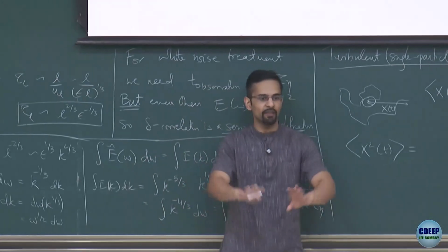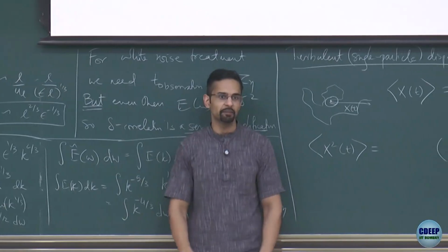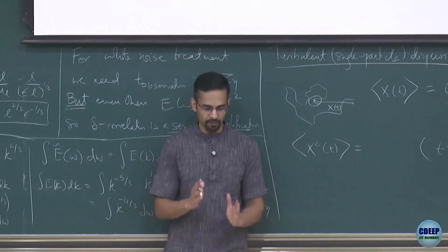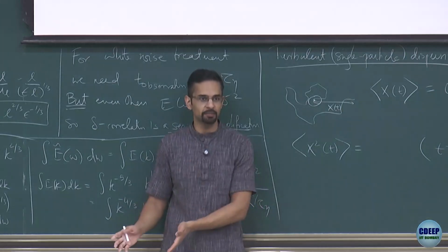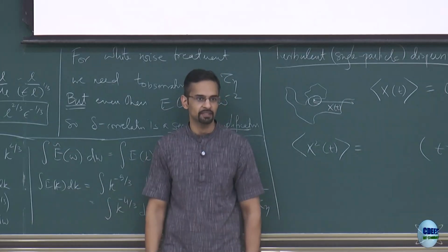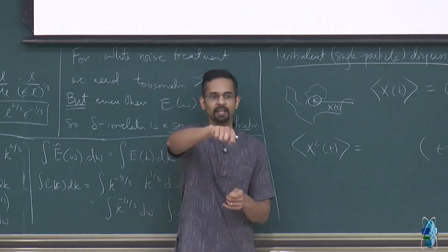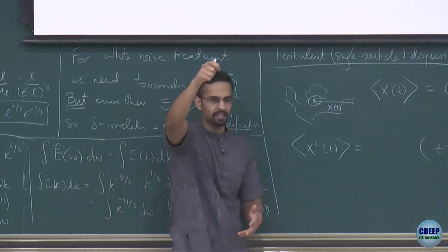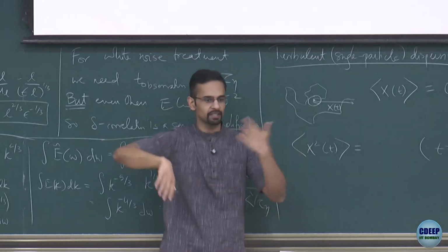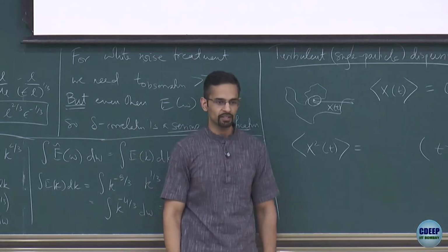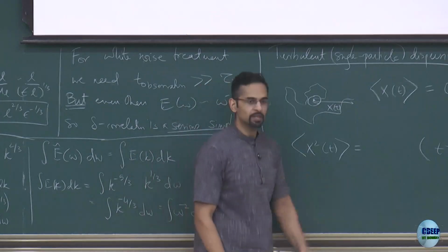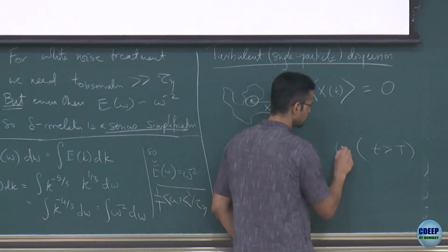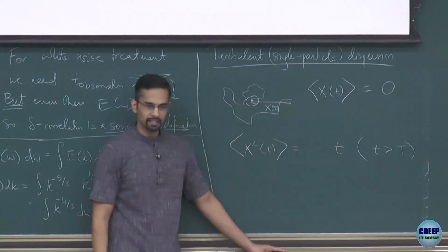The turbulent flow will have these big eddies. The big eddies are completely uncorrelated with each other. They are just moving around. So if I look at the particle across these jumps, it will look like it is taking random steps. If it goes in one big eddy, it will go somewhere. Then at the next time, it will go into some other eddy. And all these eddies are uncorrelated with each other because the flow is chaotic. And then in the end, I will do something like a random walk motion. So this x square will grow like t, just like it does in a random walk.